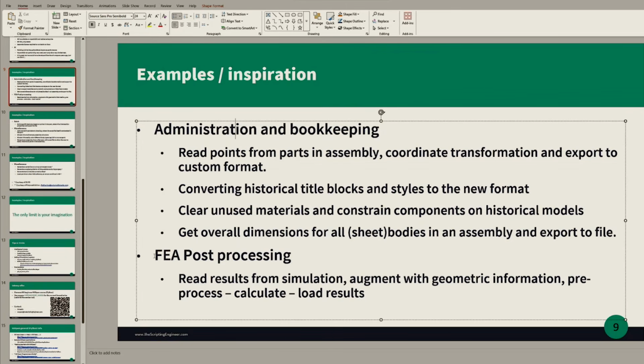There was also a question, I think in the FAQs, on could we use NXOpen and Python with FEA and Simcenter? The answer is yes. Here I have an example where I would read results from simulation, structural results on shell elements, reading the stresses. Then I augmented that with some panel geometric information for buckling, on panel lengths, different formats, that kind of stuff. That was for a marine environment.